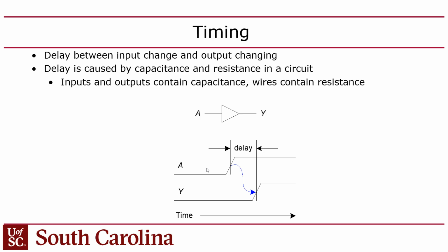That's one of the reasons why people just don't use FPGAs for all digital logic, because FPGAs are about 10 times slower, right? The reconfigurability comes at the cost of reduced logic density, which translates to longer wires and thus higher capacitance. And so FPGAs run generally at about 10 times slower clock rate than an ASIC, and you have about 10 times fewer gates on the FPGA than you would on an ASIC of equivalent size.